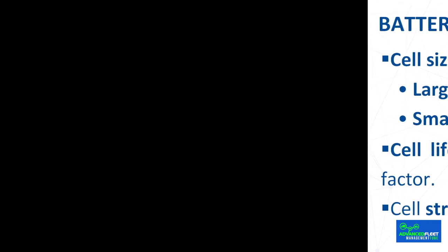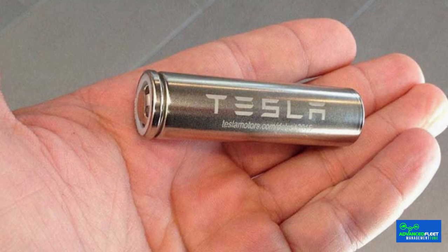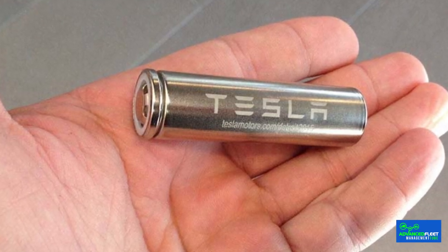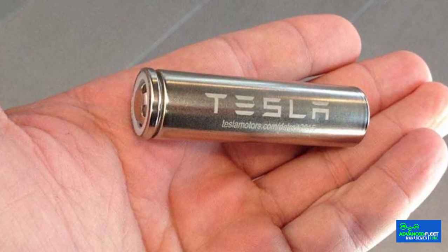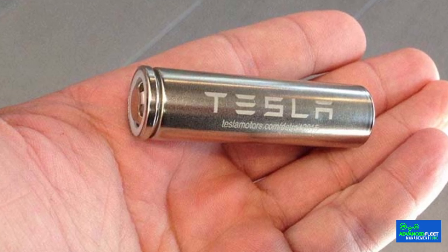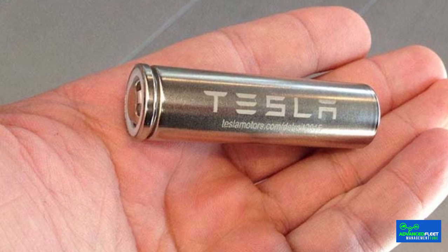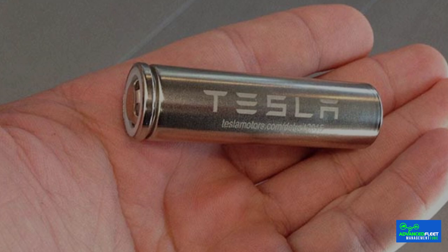Small cells. This type of cells are used due to their great availability, since they are manufactured in millions and have more competitive prices. Also for their higher specific energy and greater ease of cooling thanks to their cylindrical shape factor. The small size of the cells allows great flexibility in the shape of the pack, and reliability also increases.